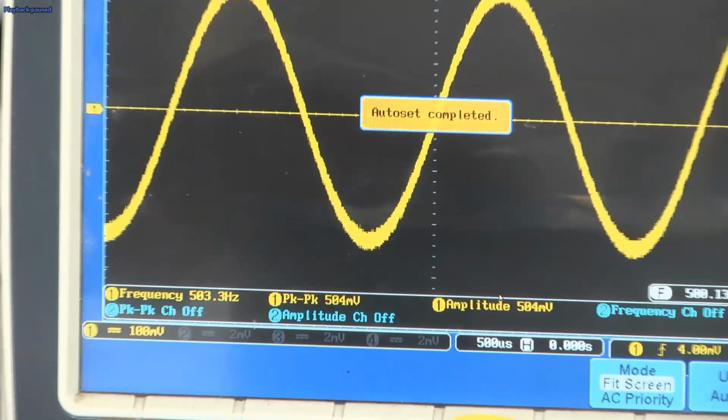So from here, you can see the amplitude value of the input signal. Here the voltage of the information signal, U information, equals 0.25. That means the amplitude of the input waveform. So we have to make this amplitude 0.25 volt, that means 250 millivolts.